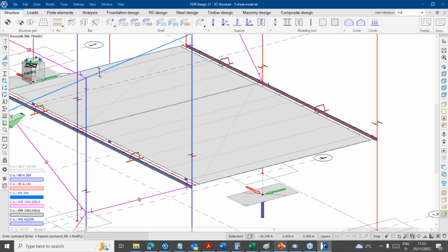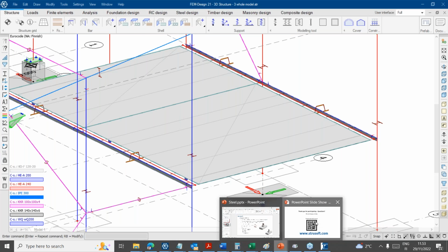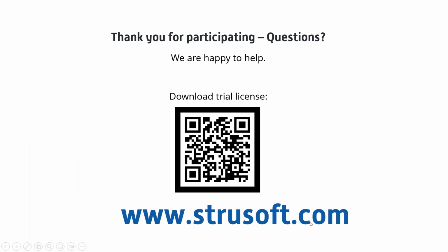So that is actually a really good model. The other good option is to use claddings, because they don't have any stiffness. If you have any doubt that you are producing too much stiffness in your concrete floors, then why not model with the claddings in the vibration analysis or something else? But the hinges will give you almost the right distribution of stiffness.